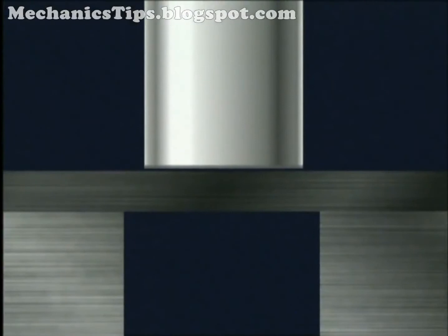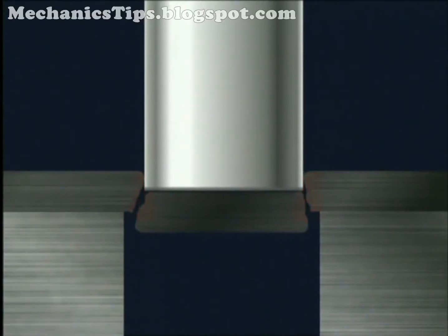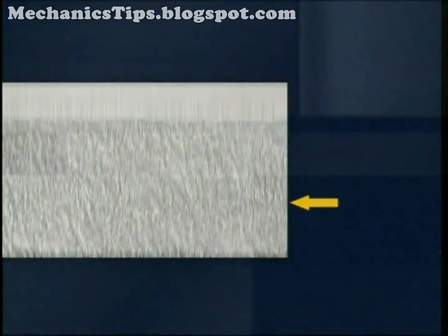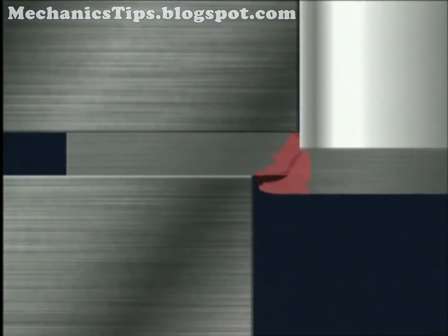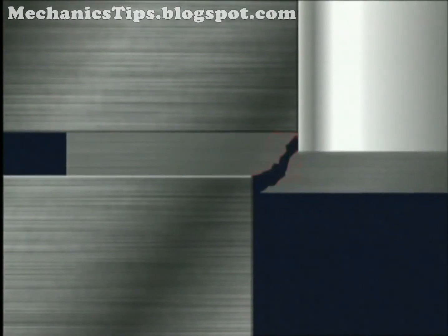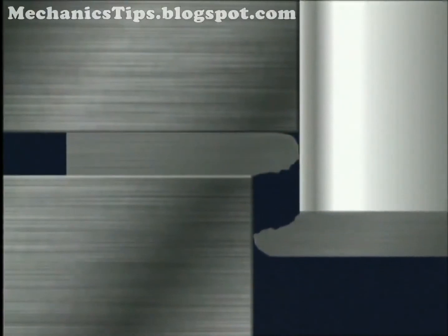During punching, the stock is stressed between the cutting edges of the punch and the die. As the punch penetrates the material, stresses build up until fracture occurs. Close inspection of a die-cut edge of sheet metal stock reveals a burnished edge where the punch penetrated the stock, followed by a rough edge where fracture occurred. Mild steel generally separates when approximately 1/3 of the stock thickness has been penetrated. However, when harder materials are die cut, penetration by the punch may be less than 1/3 the material thickness, and softer materials may require almost full punch penetration before fracture occurs.